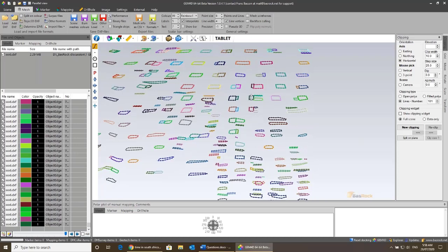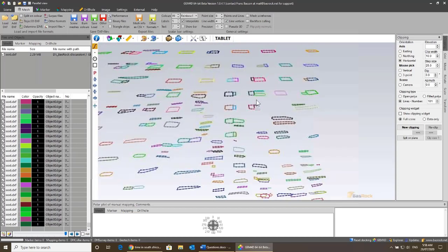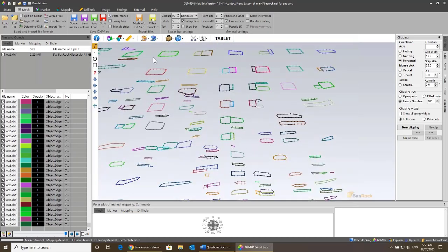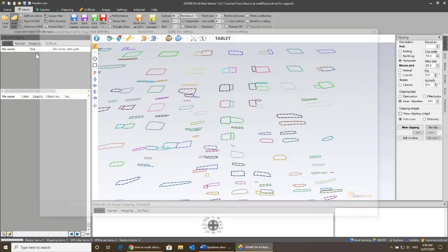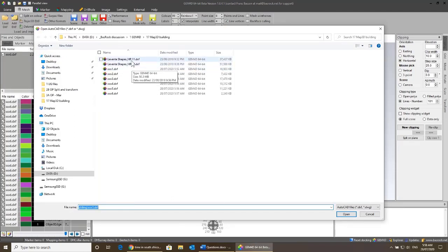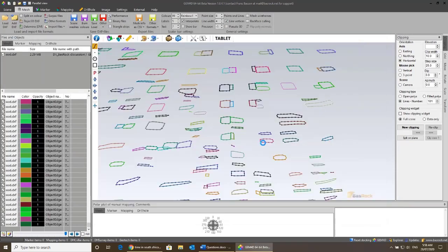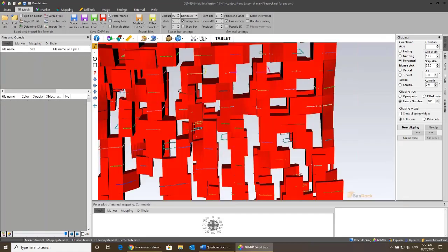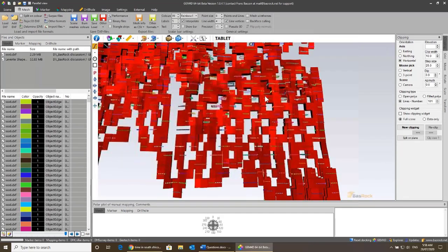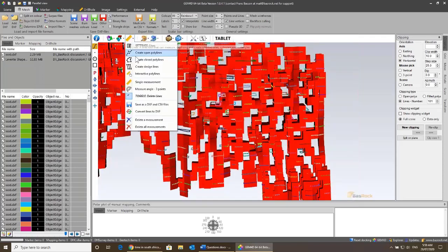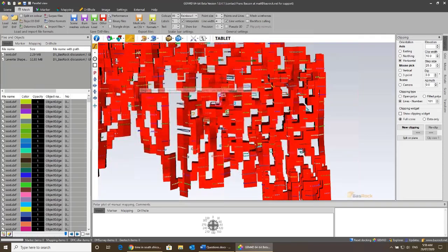For that, I need to know what the dip angle of this ore body is. So I should have met that. Let's load the mesh and get the dip angle from the mesh. I think that's going to be the best. So I'm just going to load back the meshes for a moment, just to get the dip angle. You can do a few tests, but I'm not going to go through too much detail. I'm just going to do a single measurement, and whatever the value is, I'm going to choose.